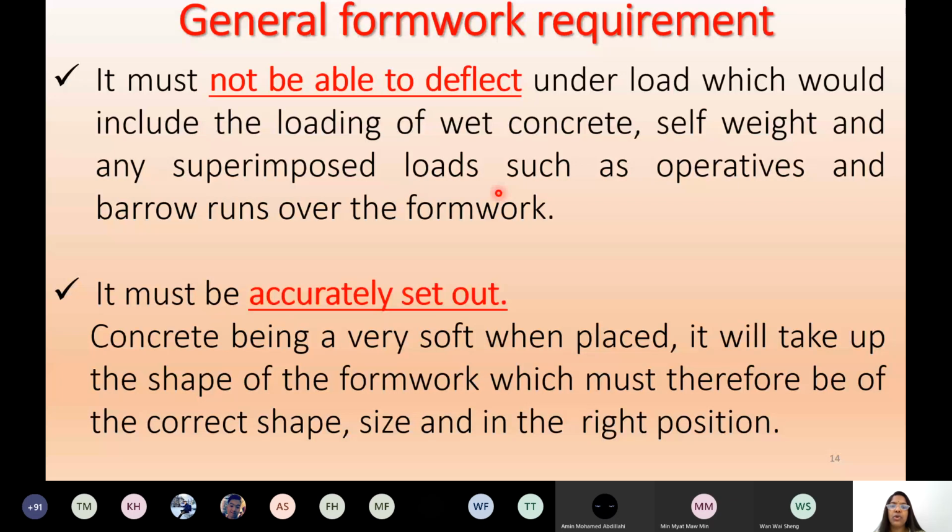This deflection can be overcome by proper spacing, proper fixing, especially joint to joint. It should be connected center to center, right, center to center. These things are very important to take care of. Once the formwork is done, as an engineer, you go to the site and check the spacing, whether the center to center is followed, and how much packing is done at the bottom for holding the pole. All these things you have to check. You can even cross-check whether it is viable or about to fail, and then confirm it, approve it, before you go for concreting.